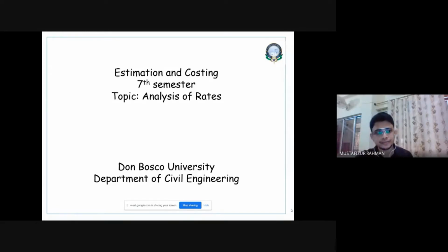So we have to have some engineering judgment and experience in how we deal with these numbers, how we estimate the amount of labors required, because material required is almost fixed. We can calculate the materials required from our specifications and dimensions of our building. But what will be the labors required? It is dependent upon how skilled and how experienced those people are, so it will vary from place to place, from time to time.